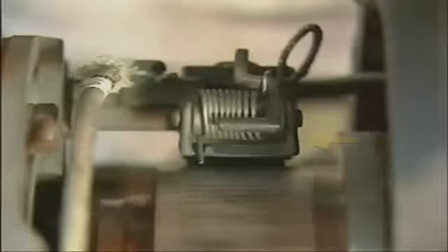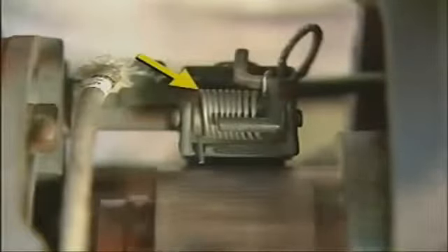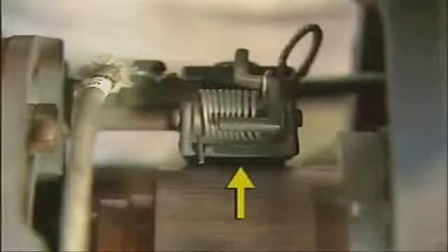To do their job properly, the brushes must make full flat contact with the commutator at all times. This contact may not be possible if the brushes are hung up in the brush holders, if the brush pigtails bind on the brush holders, if the brush tensioning devices are set incorrectly, or if the brushes are too short. Full contact between the brushes and the commutator is also impossible if the brushes are broken, cracked, or chipped.